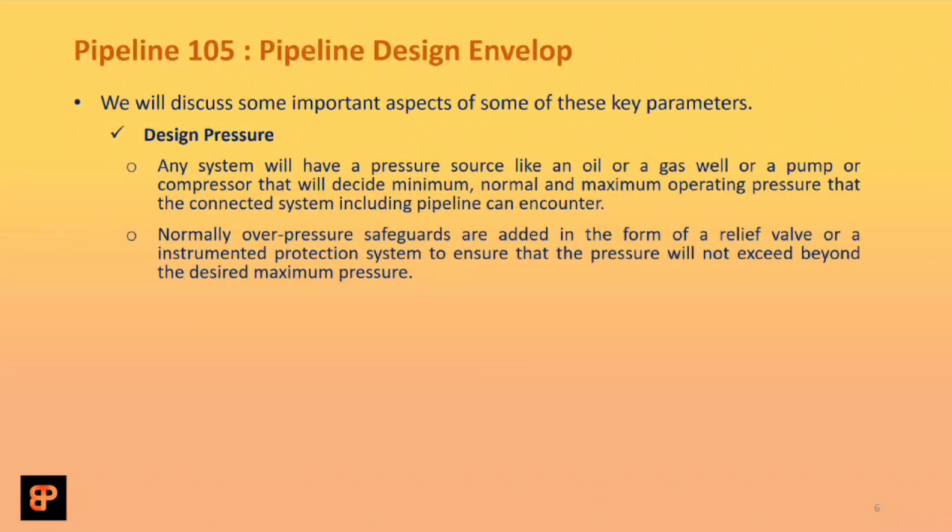Upstream of such a protection system or valve, locally only it can be designed for high pressure, which will be limited to only shorter lengths, but the majority of the lengths can then be designed for reduced design pressure, because the safeguards will work.